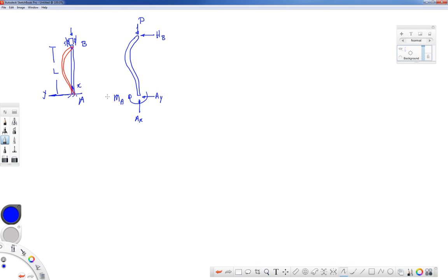In our coordinate system starting down here, I'm going to take and make a smaller free body section at distance x to figure out what our internal moment is. We're going to apply EIv'' equals M again, like our beam equation. So I'm going to cut this at position x, and I'm going to draw the free body diagram. I'm going to draw the top part of it.